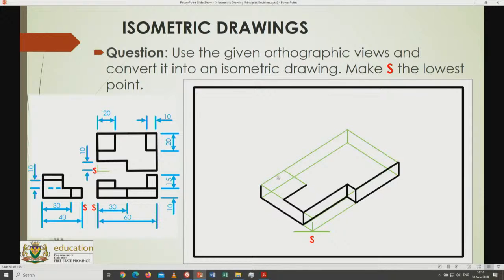So you have to measure those blocks out once you are at that level, and once you're there you can extend it upwards. And the same with the block at the back. First measure it out, and then it has to go 15 millimeters higher, so therefore we go 15 upwards, and then the size of it will be completed on the top, which is that line at that end. So there's still ends that need to be drawn in as dark lines, which is that line over there and this line over here, so we have to complete that for the complete drawing.